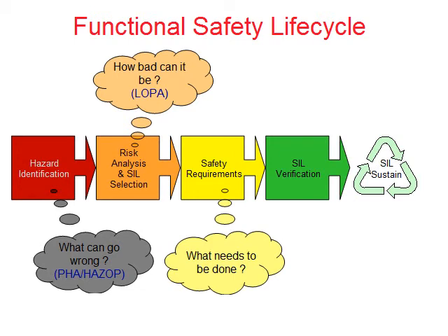We'll call it in general the step 2 is done, you need to determine and document. So in step 2, we've determined how much risk reduction we need. So now we need to document exactly what must happen. Now this is really a critical thing, because to say, oh, I need to detect, let's say we're concerned about the risk of nitrogen asphyxiation, need to detect nitrogen near reactor 103.